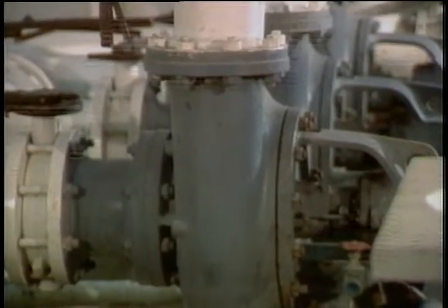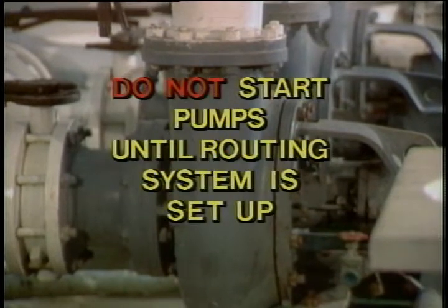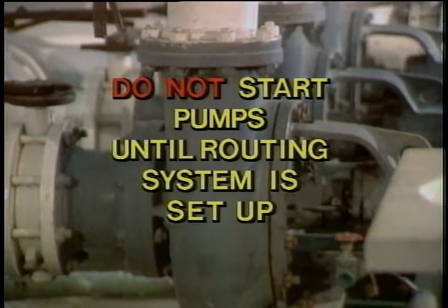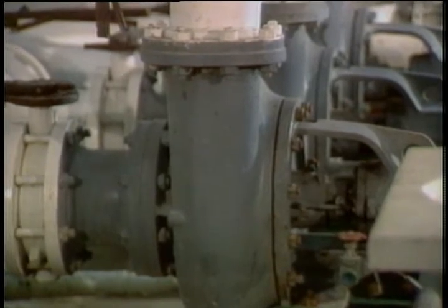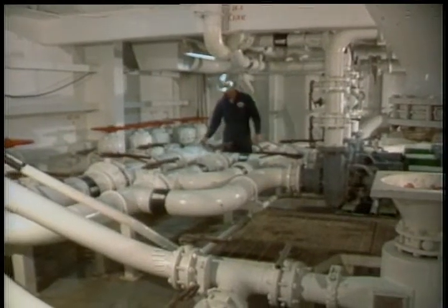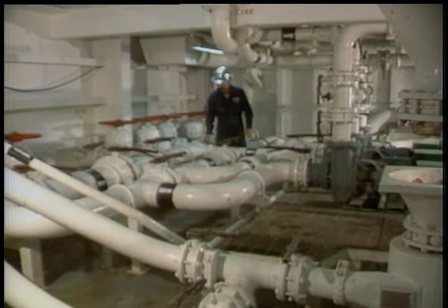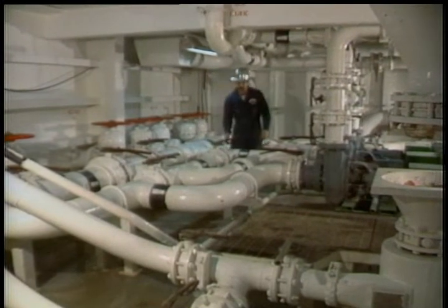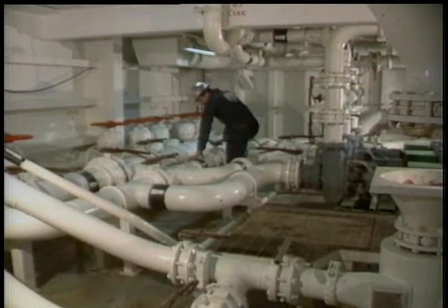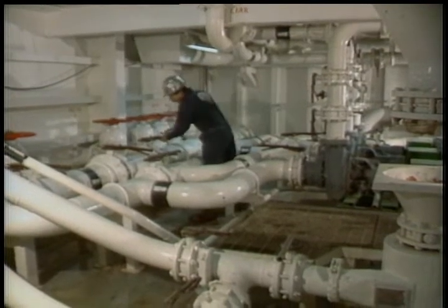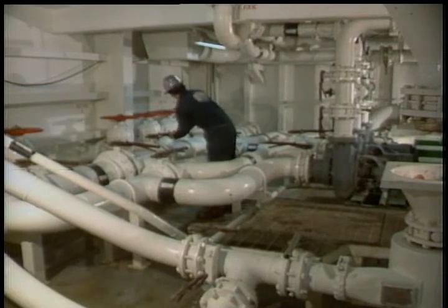The one thing to remember here is not to start any of the centrifugal pumps until you have your routing system set up. You don't want to run these centrifugal pumps dry, and you don't want to restrict the output. The best way to learn the system is to go out there and practice lining up your flow from different source tanks to destinations. Don't wait until you're under pressure from the driller to do your learning. Learn the system ahead of time and get comfortable with it.